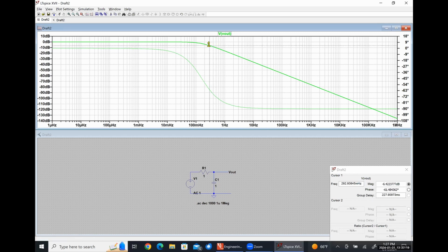So just going back to where we were. All I'm doing is looking at the table on the bottom, and I'm trying to get the magnitude as close as possible to -3 decibels. When I did that, I can see that the associated frequency is 159 millihertz. Okay. So this is a low pass filter utilizing a capacitor. Okay. Any questions before we go back to note related stuff?